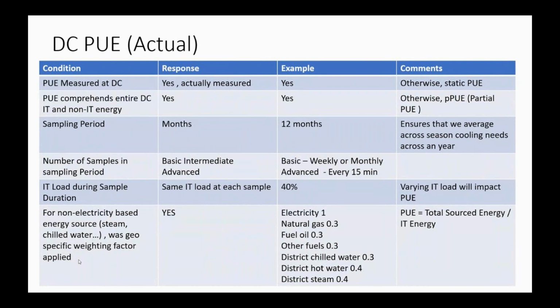So now, if you wanted to have a write-up of what we would put in a document, these are the things that we need to include. Is your PUE measured at a data center level? The answer has to be yes. It's actually measured, not some static value. Otherwise, you're a static PUE. Does your PUE actually comprehend the entire data center, not some circle that you drew around some specific IT equipment? And the answer has to be yes.